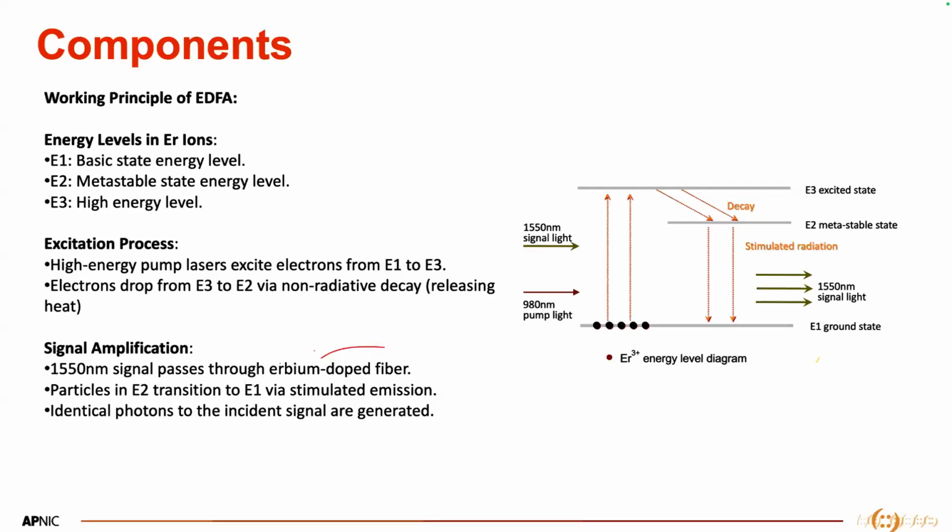When we pump, the lasers go to the high energy or excited state, and then after some time, they decay in energy and come to the metastable state. In that metastable state, these pumped energized photons are combined with the incoming signal.